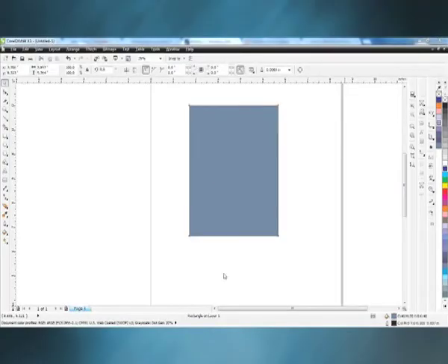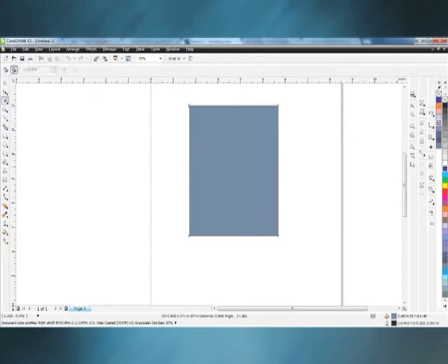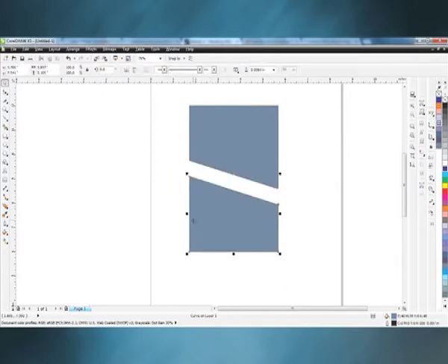To apply this, select this option, click on one end of an object and close your path to another end of the selected object. After doing so, select pick tool, click again on the object which you cut down. You will see that it is divided into parts and you can easily separate them.